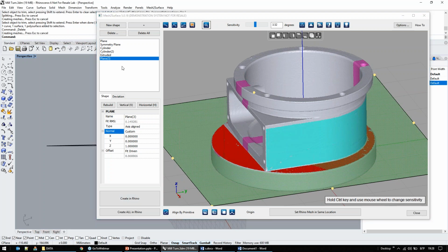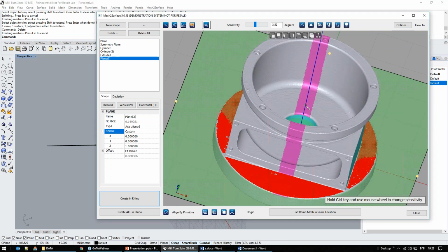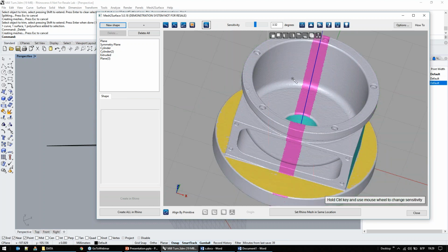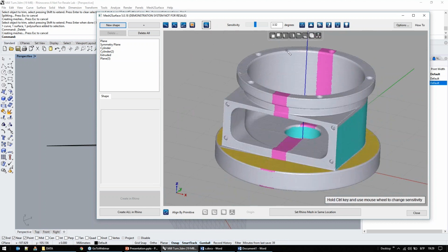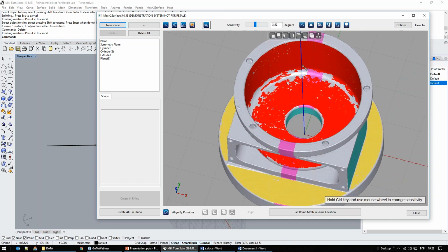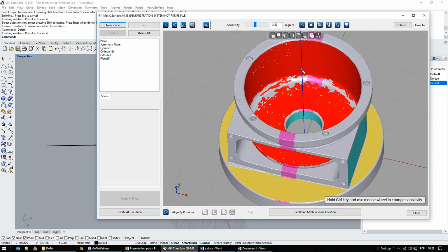You can take all the shapes and put them there. Let's go a little bit into the revolved surface. I will create a new shape, and if I look at this part, it's actually a revolved surface. The revolved surface works in a similar way to extrusion, but you need an axis for the rotation. Again, you just select what you expect, and I will select front-facing only mode, just to make sure I don't select anything from the side.